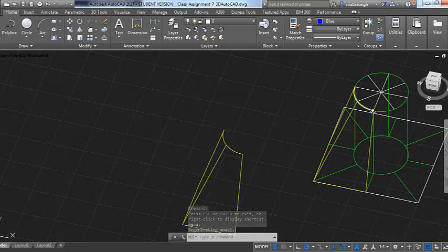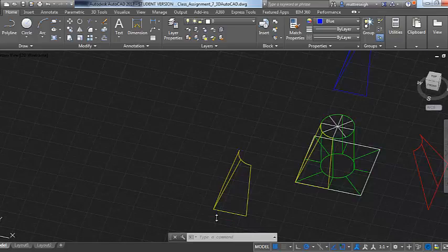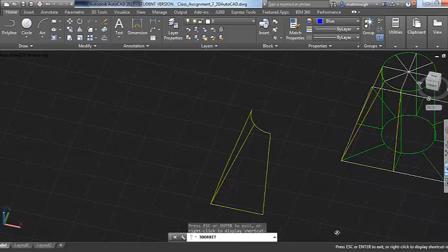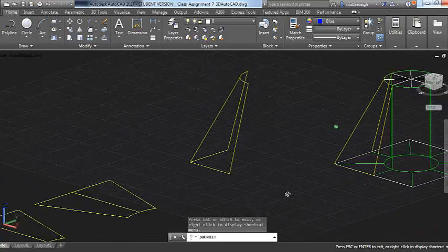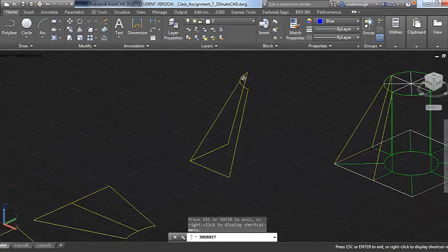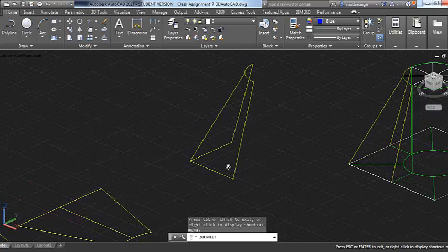All my press brake work on the round from the center line out is going to be press broke down to this single corner. Now, what I have to do as a press brake operator is turn that part 90 degrees on one corner when it's in its flat position, and make this go round at the same time. So that becomes a little trickier. All of these round press brake works have to work to the same corner and turn that thing 90 degrees. So that can be tricky.